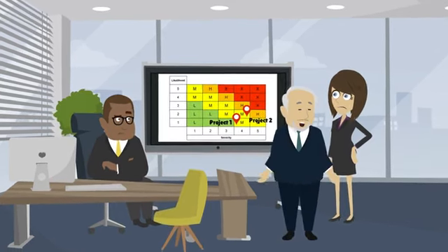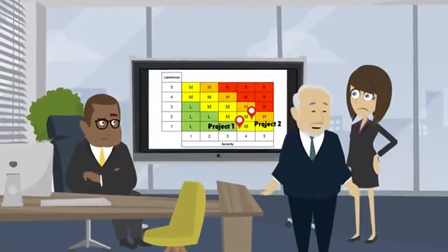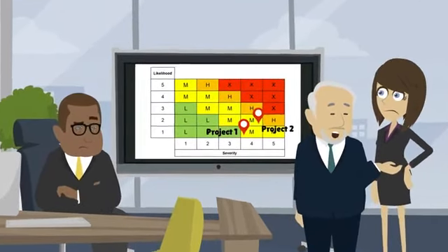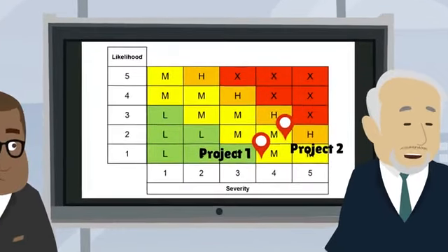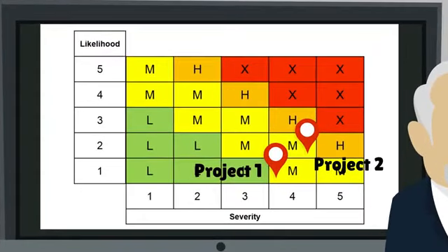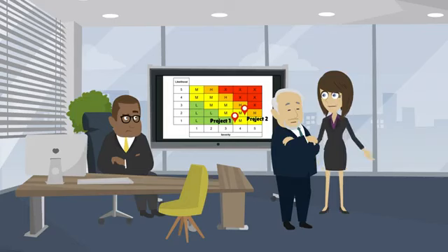Well, we did a HAZOP, and it looked like we had enough safeguards in place. It was medium risk, higher severity, but a low likelihood based on the group consensus. At this risk level, it's based on the discretion of the PHA team as to the action taken. Are all your PSVs sized correctly? In our HAZOP, we had one overpressure scenario where the PSV wouldn't relieve fast enough, so it required a high-integrity pressure protection system. The design does have a high-pressure shutdown.